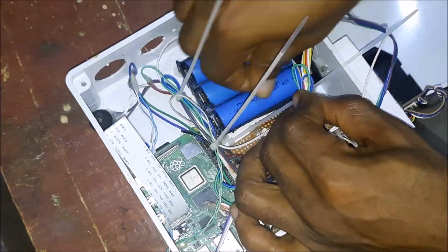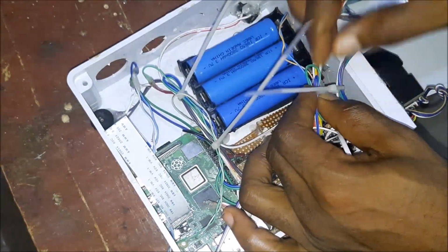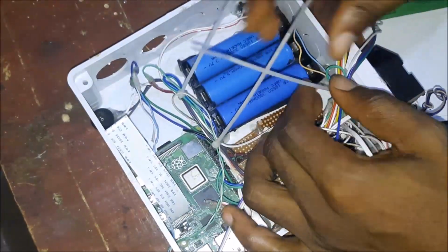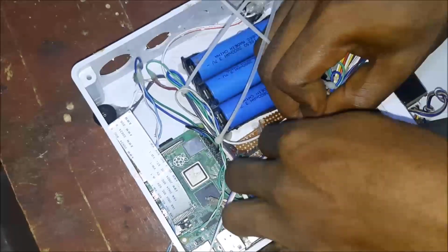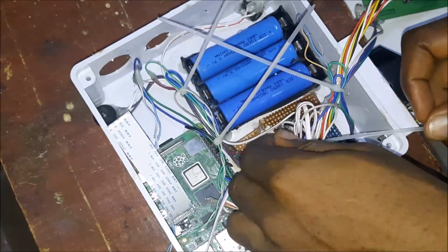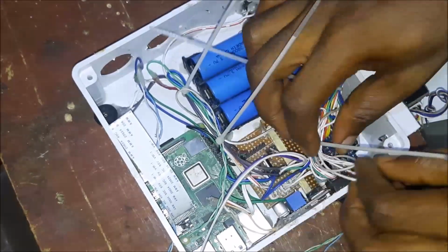As a backup, we used some series-connected 3.7 volts LiPo batteries to power the project design. Since the project itself was meant to open a 12 volts DC solenoid lock when the face and fingerprint verification was successfully passed, these batteries could be recharged by plugging them to a 12 volts DC charger.